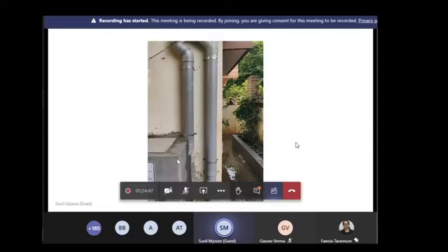You're not storing anywhere. Coming back to first rain separation, this is how a typical first rain separation looks. You can see the water column with the valve fitted. When the valve is closed, the water builds up in this pipe. That is essentially wasted every time you open that valve, and the water keeps going out. It doesn't get into the filter. When you don't want to use the water, you can keep the valve open.